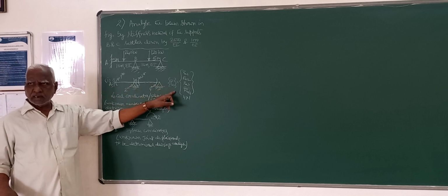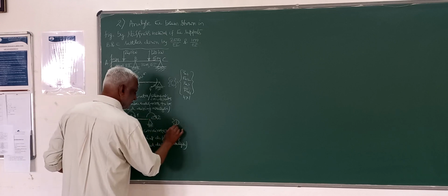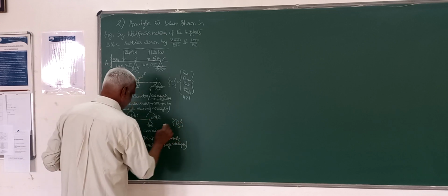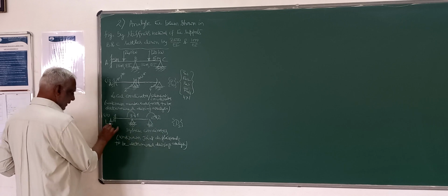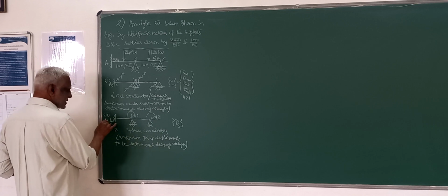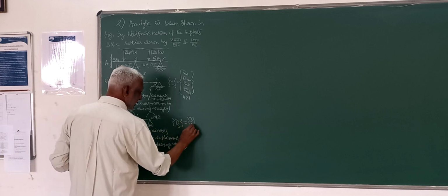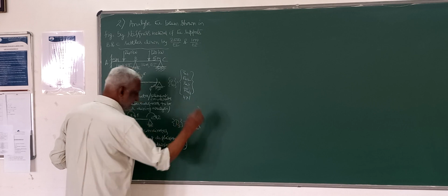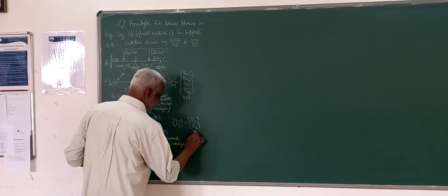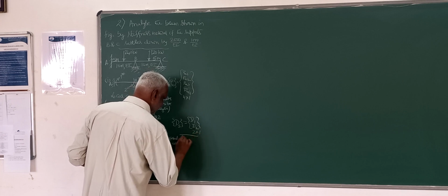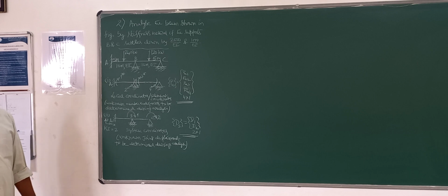The unknown displacements are these, that is D, with respect to global coordinates. With respect to global coordinates, we have to determine these unknown joint displacements D1 and D2. That's what we have to determine. It is a 2x1 matrix. So these are the two things which we have to evaluate during the analysis.